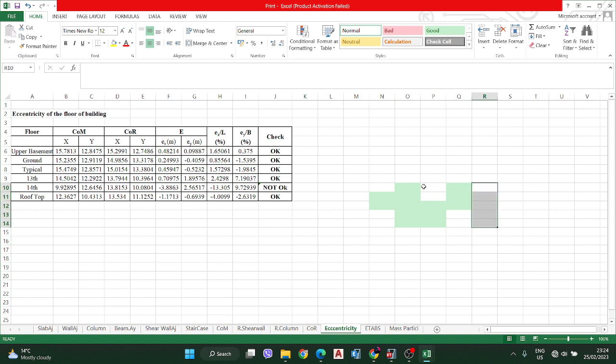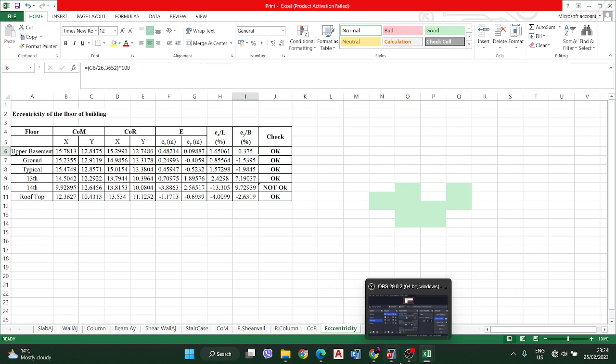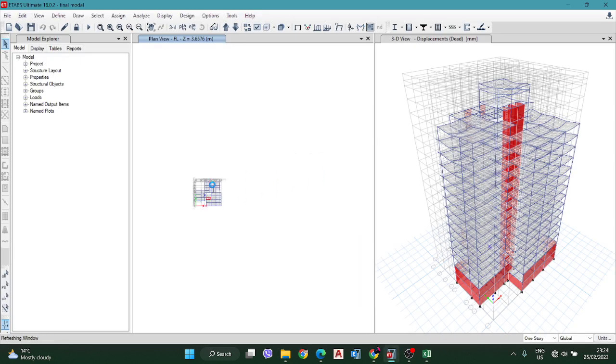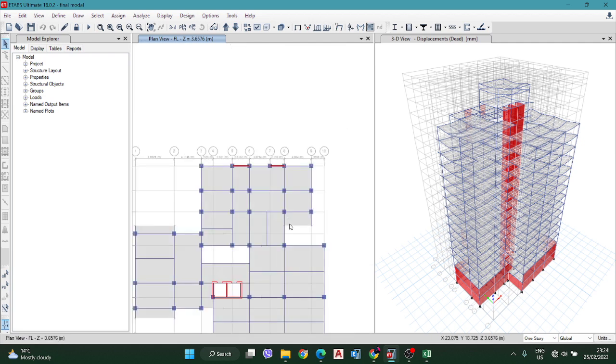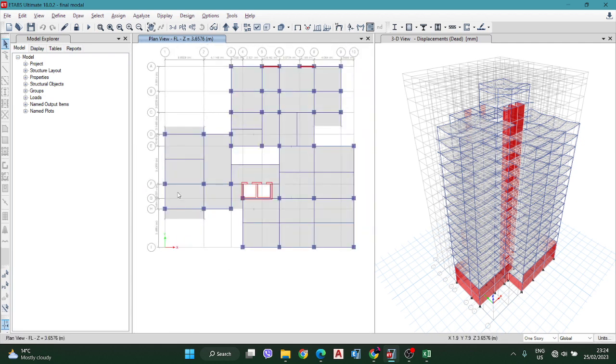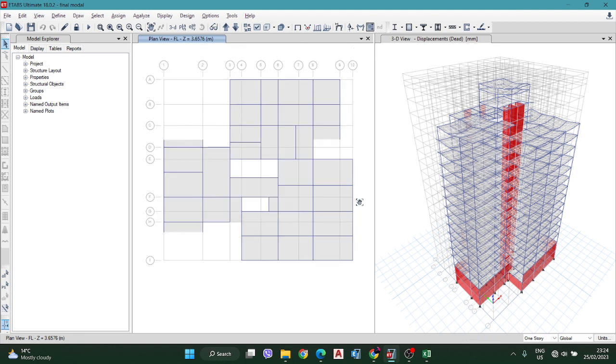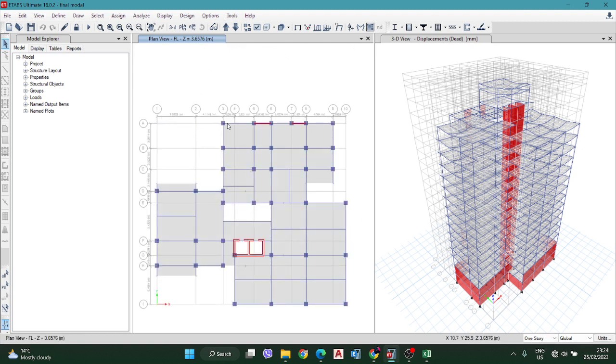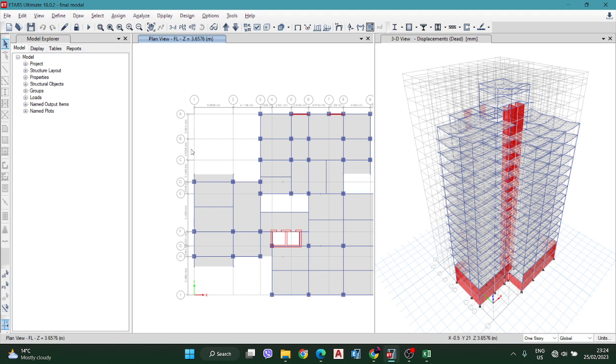If in an upper floor there is a gap, a lot of gap, you still have to use the maximum length of x, here to here. That is the maximum length x. Use that for L, and for the maximum B, here to here. For the global X, that means here to here, just sum all these values for X, and for Y, just sum all these values.